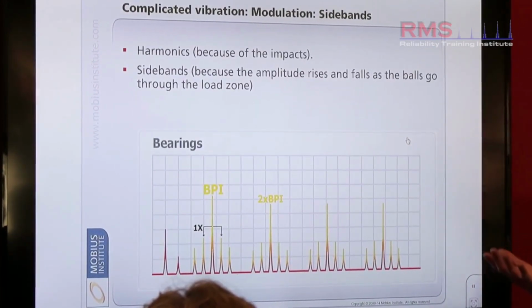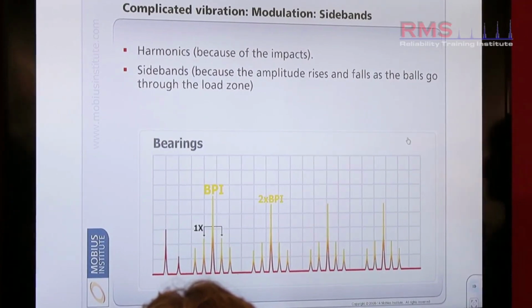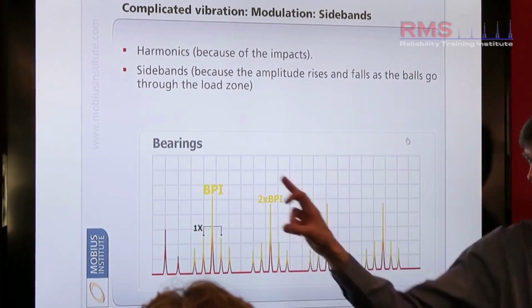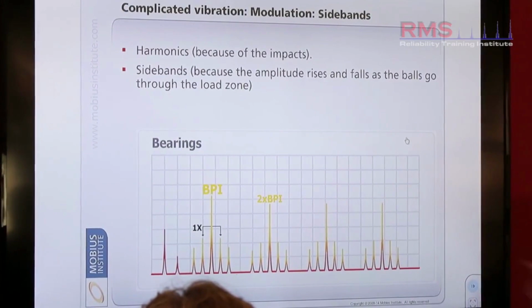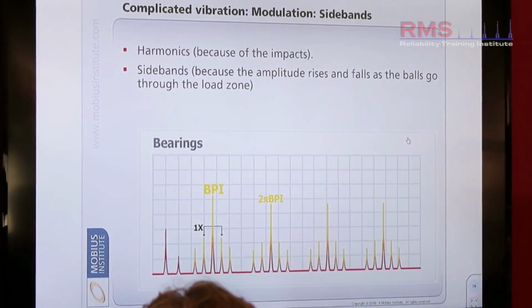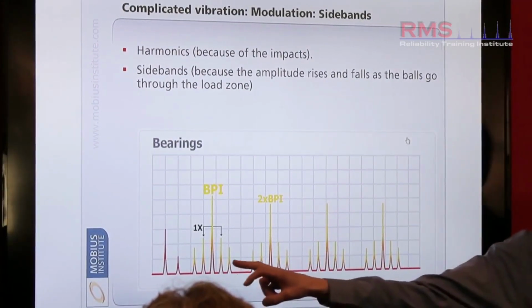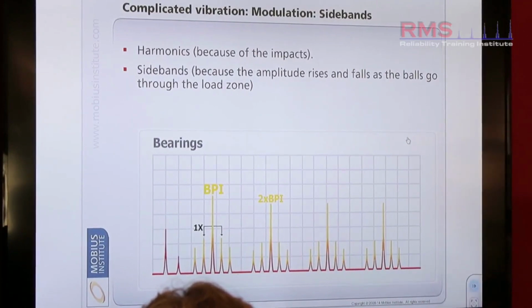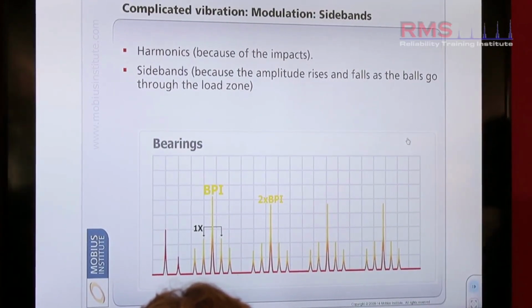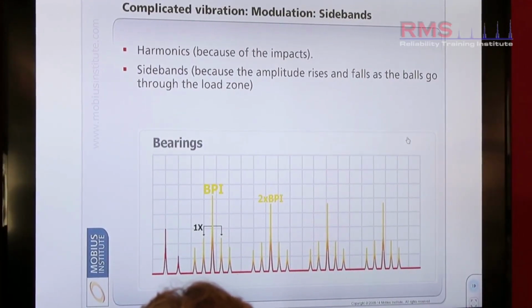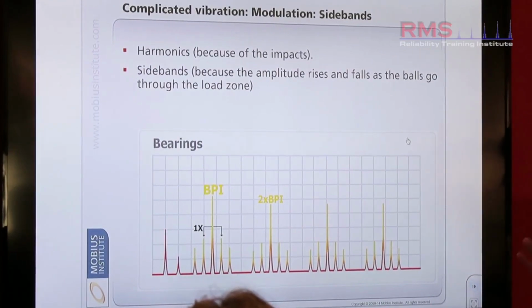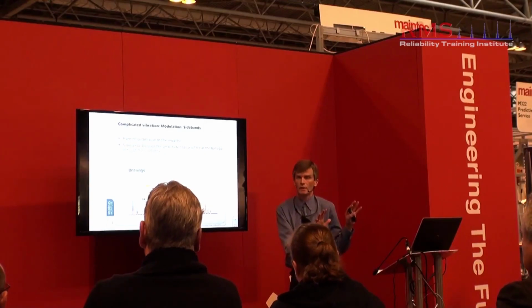But we've got shock as well. So what do we see? Shock results in harmonics, equally spaced peaks, the larger ones there in yellow, and sidebands where we see equally spaced peaks around those harmonics. Maybe that's one step too far for those of you that are newer to this subject, but distinctly different pictures to simplify.